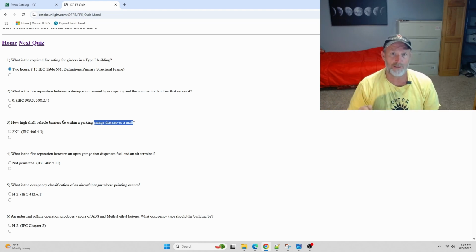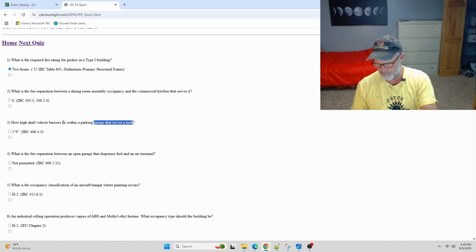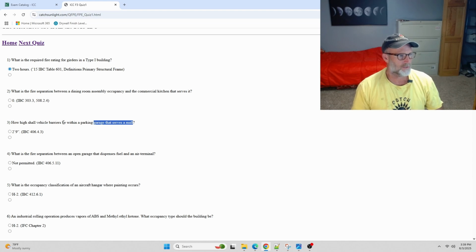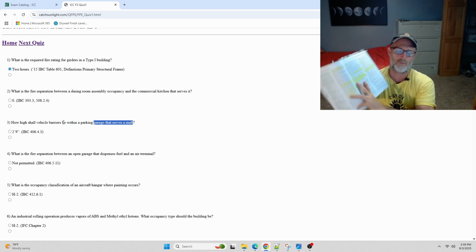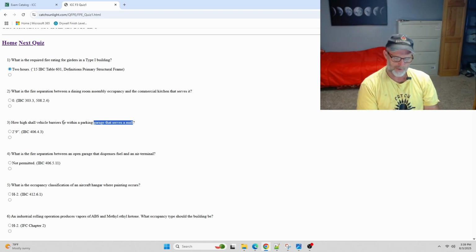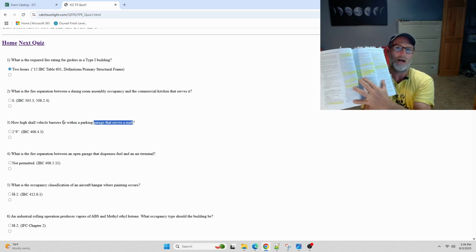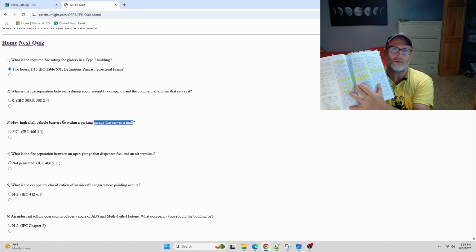Chapter 4 of the IBC covers malls. But I give you the reference, 406. Let's jump into 406 and be very specific, make it easier. Chapter 4 covers specialized stuff. If I go over here to 406, the sub number is 406.4.3. So right here, I have my middle finger on it. That's 406.4.3, and it says vehicle barriers not less than 2 feet 9 inches. Bam, there's your answer. As you can see, I have it highlighted and I have the answer underlined.